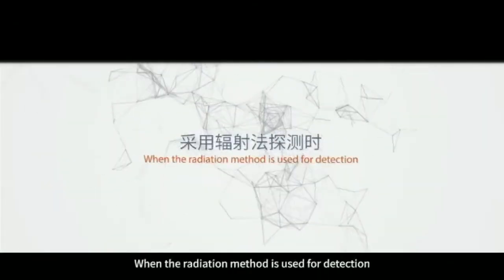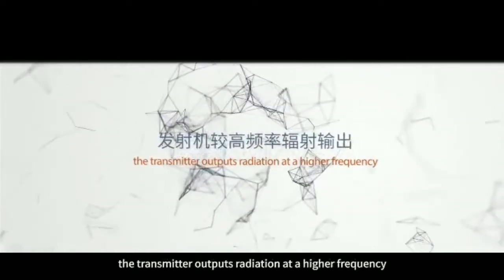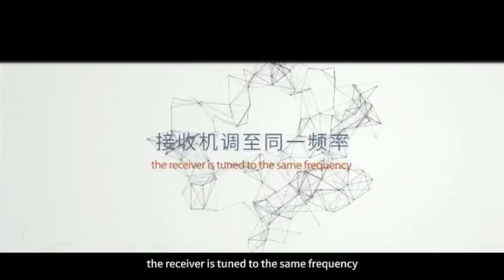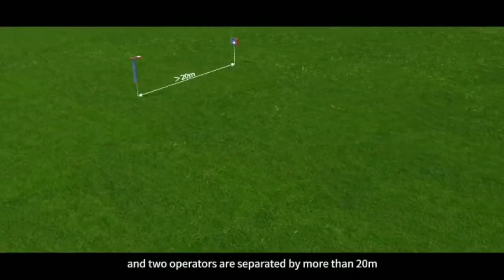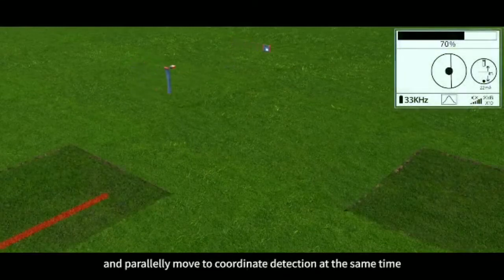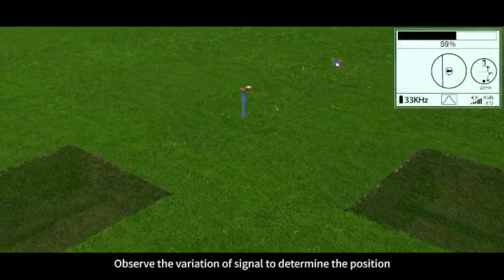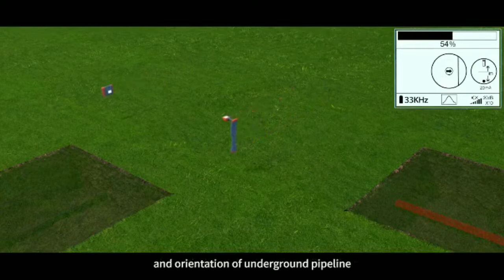When the radiation method is used for detection, the transmitter outputs radiation at a higher frequency. The receiver is tuned to the same frequency, and two operators, separated by more than 20 meters, move in parallel to coordinate detection at the same time. Observe the variation of the signal to determine the position and orientation of the underground pipeline.